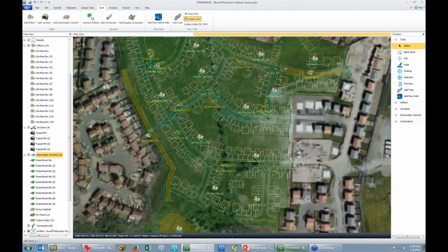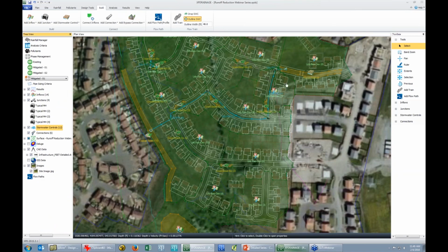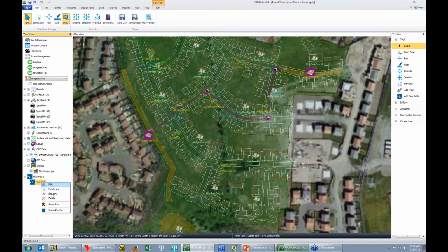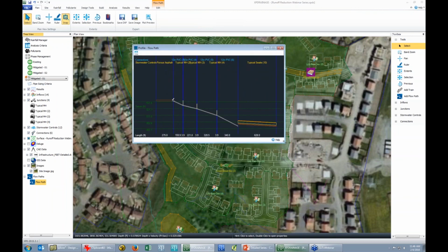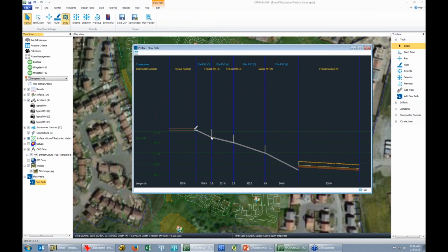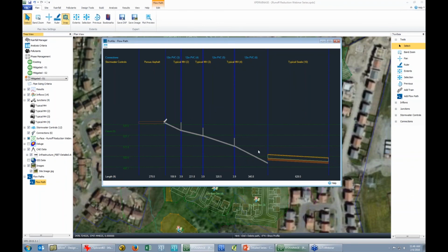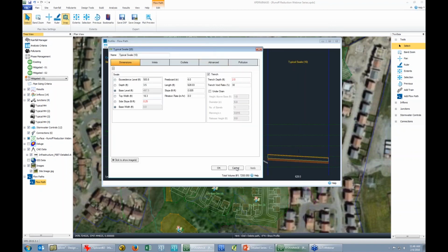So as we're building, this is great, this is fine, but I want to maybe see the verticalness of this. I want to see a profile. So I can add a profile, and I could go from here to here. I could see our first pass. You'll see our pipes were automatically connected to the base of those manholes. Okay, makes that really easy when you string them together. We add these together, automatically attached to the base, attached to the outlet. You know what, hey, this is a little deeper than it should be because we placed that in the middle of the area. Didn't really pick up the elevations right. Well, I could manually go and change these profiles. Again, I could update the profiles, update our facilities themselves by double-clicking on that profile.